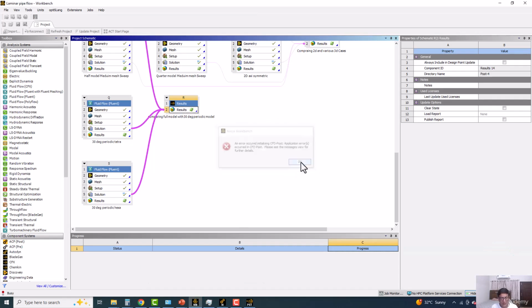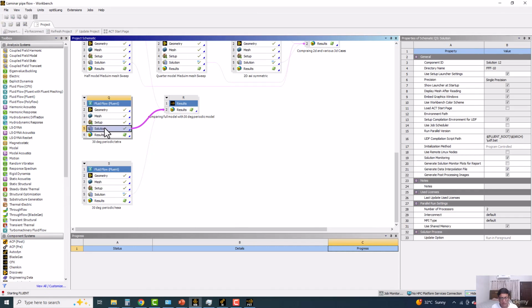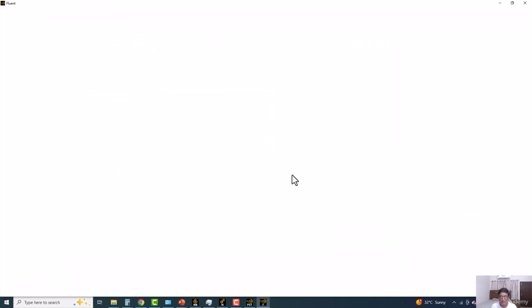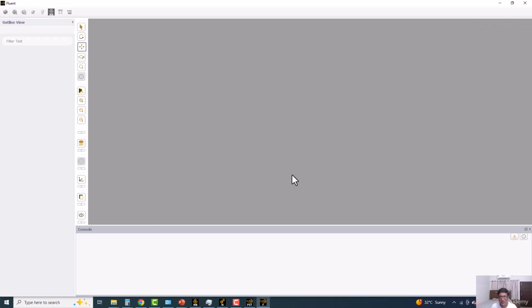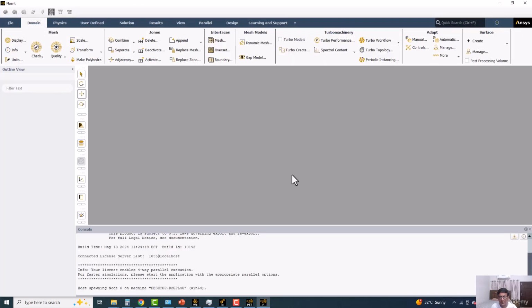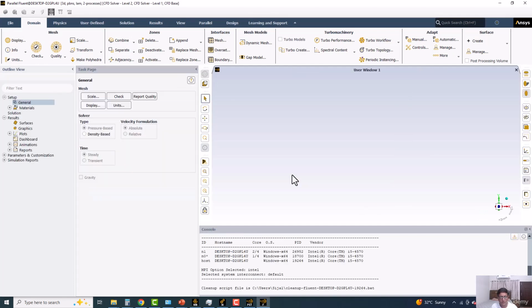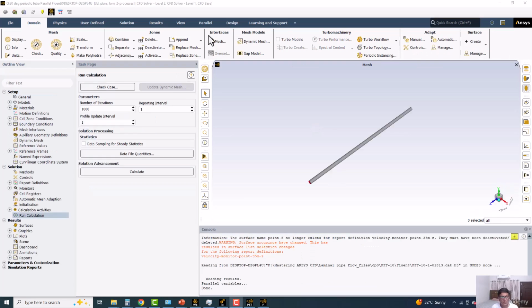So what I suggest is that if I go to solution and rotate the geometry by 75 degrees along the z direction, both periodic cases, hexa meshing and tetra meshing, will be exactly on the same location. And then when we draw the vertical line, that line will still be valid. So let's do it.